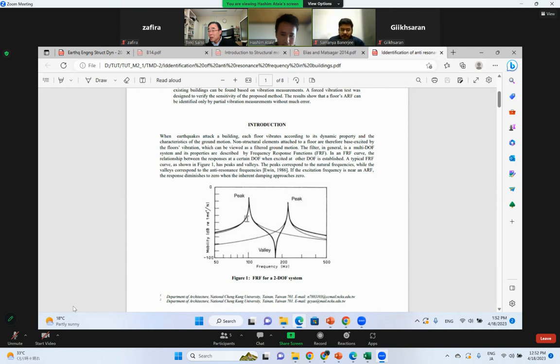This is the first mode frequency. This is one anti-resonance frequency, and there is another anti-resonance frequency. Yes, Sensei. The anti-resonance frequency is where, when excitation is applied at that frequency, the response of the structure is 0.